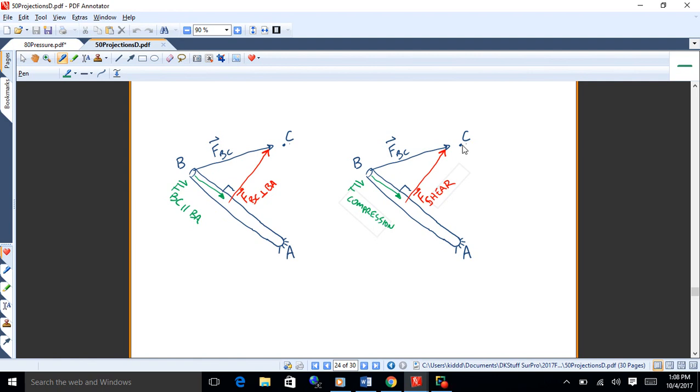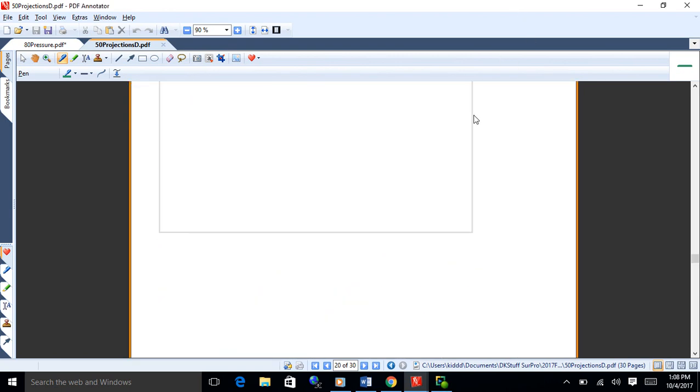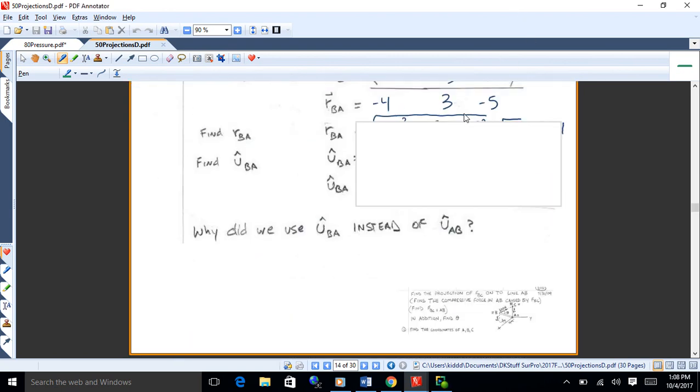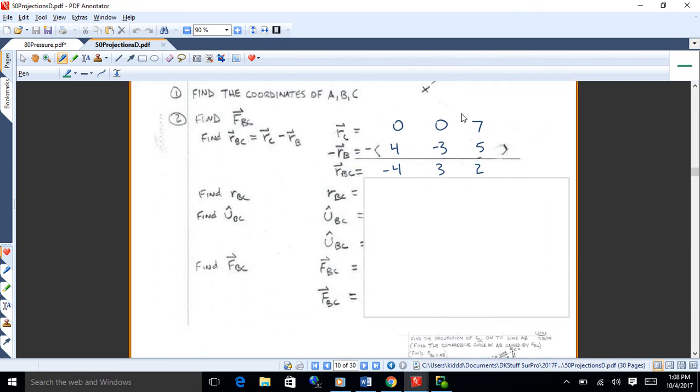Does tension and compression just differ by negative? Yes, tension and compression are just different signs. What tension and compression do is they stretch the atomic bonds or compress them. Think of the bonds being like springs. What shear does is it slides one plane of atoms across another. So that's why we're doing this.